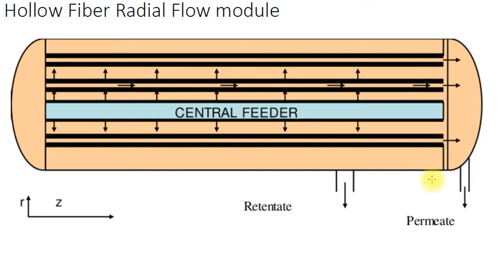So the fluxes are low, but you want to increase the membrane surface area so that you get good recovery. For that you use very thin membrane fibers, which give a very high fiber surface area per unit volume, and you get good recovery of the permeate.